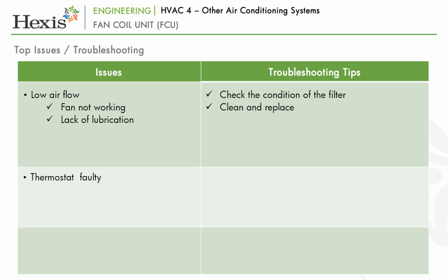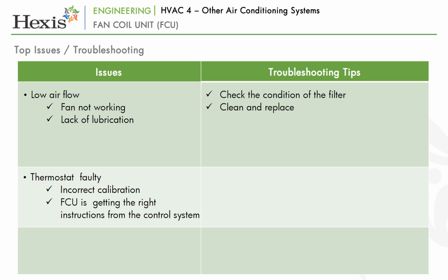Especially if you still have the old dial-type thermostats, they could be incorrectly calibrated, which means the FCU isn't getting the right instructions from the control system. This problem is fairly easy to fix by replacing or recalibrating the thermostats.